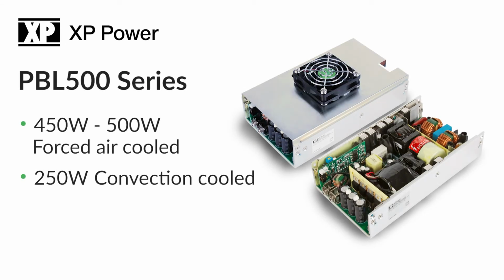Our first option is to look for products with separate power ratings for convection cooling and forced air cooling. In a convection cooled application, the average power would be supported by the convection rating, and the peak power may be supported by the forced air rating if this is greater than the peak and after careful consideration of the duty cycle. An example power supply would be the PBL 500, which has a convection rating of 250 watts but will run at 500 watts with forced air.